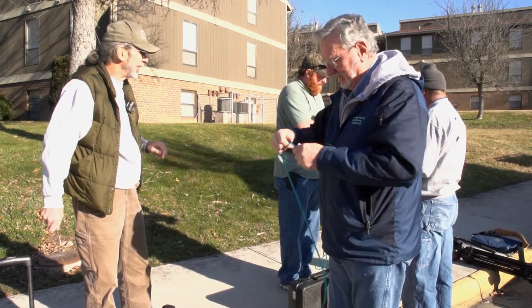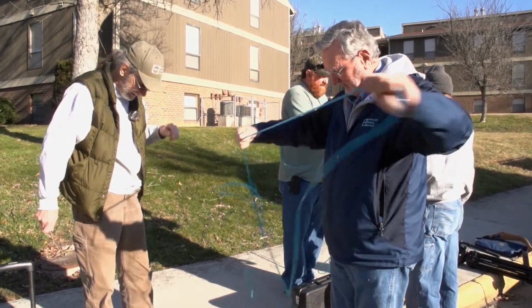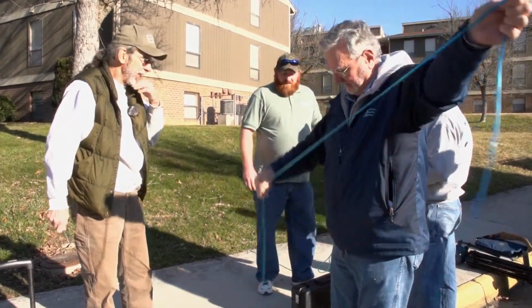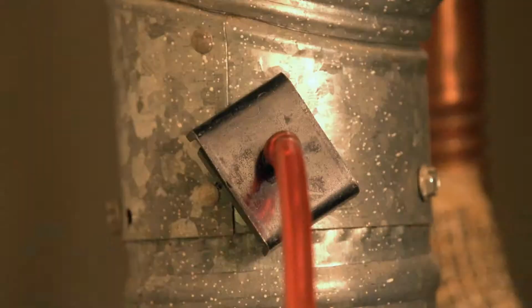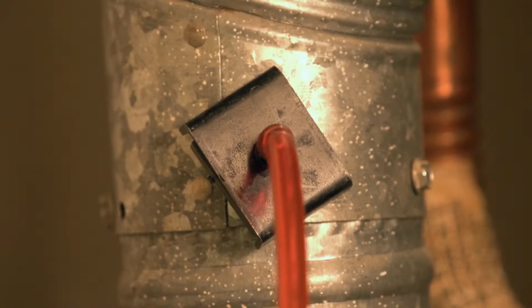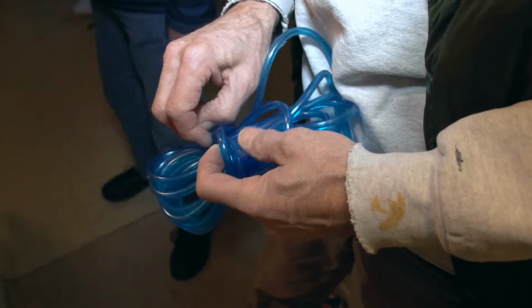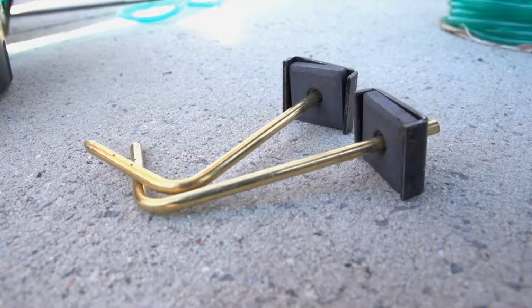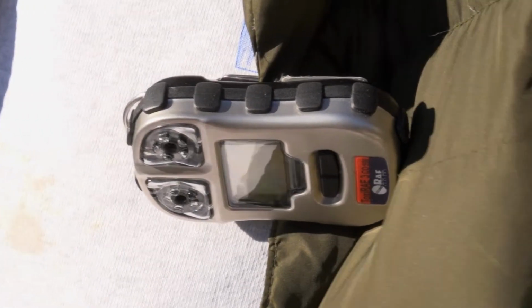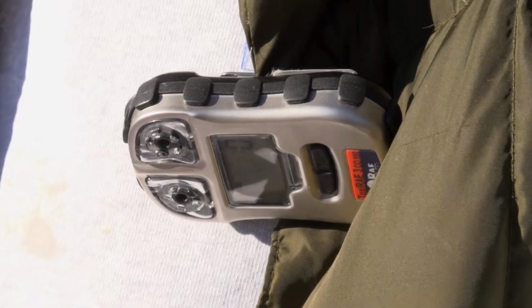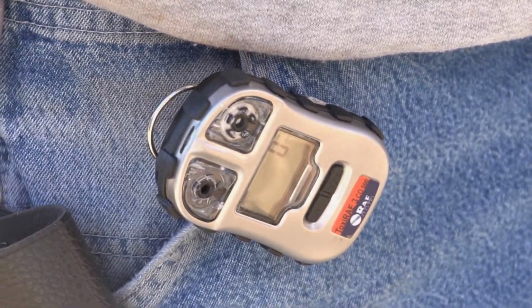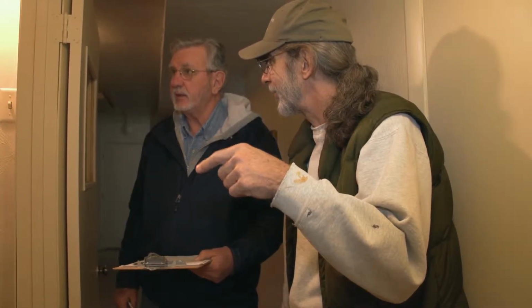You're also going to need several lengths of reference hose. One of these is for checking pressure to the outside of the house, another for your draft gauge, and another for checking room-to-room pressures. You're also going to need a draft gauge for inserting into the chimney and checking the actual draft of the appliance. And most importantly, you're going to need a personal carbon monoxide monitor. This is to ensure that during the test, you're not exposed to dangerous conditions inside the house.